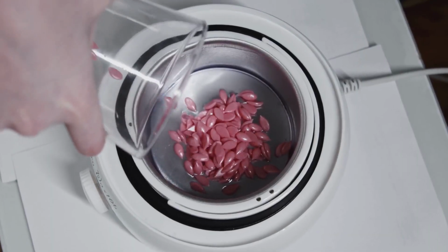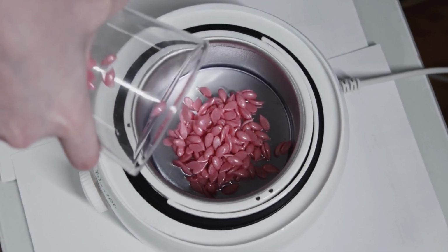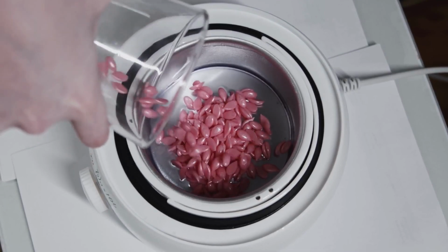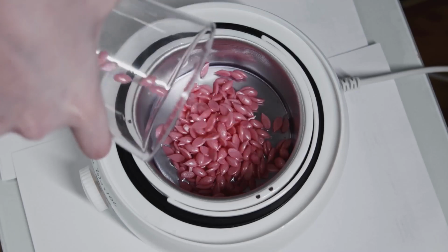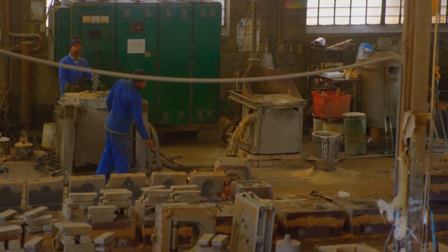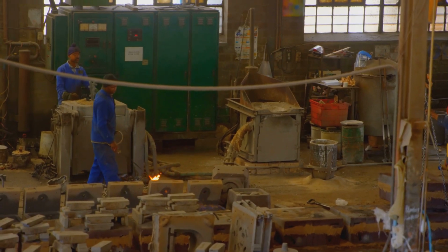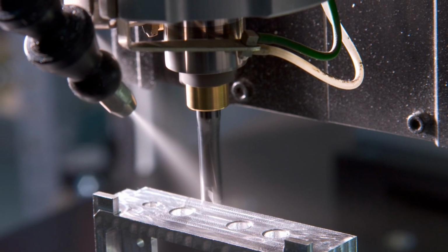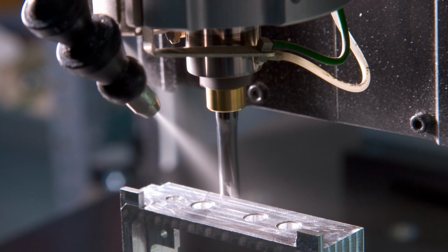First, we mix wax and pigment, the essential ingredients that give crayons their color and form. This involves precise measurements and careful blending to achieve the desired hue and consistency. Next, we heat and mold the mixture, transforming it from a liquid state into the solid crayon shape we all recognize. This requires specialized machinery and precise temperature control to ensure the crayons are formed correctly.